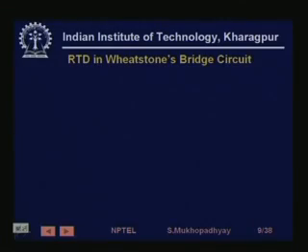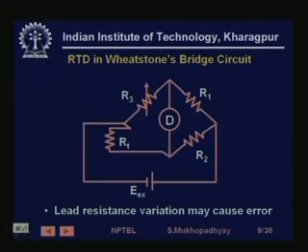So you have an element whose resistance value changes with temperature. Now how are you going to generate an electrical signal out of this resistance value? One of the simplest ways, as we have seen, to convert a resistance value to a nearly proportional voltage value is the DC Wheatstone's bridge, which looks more or less like this.